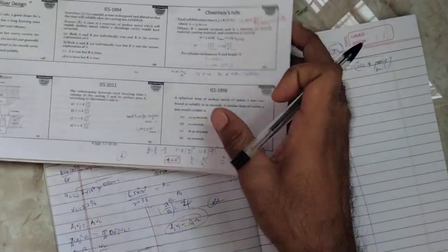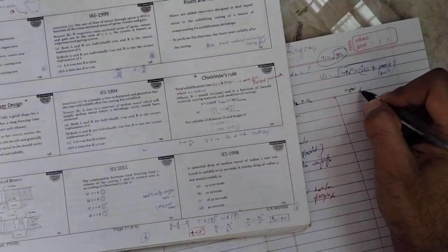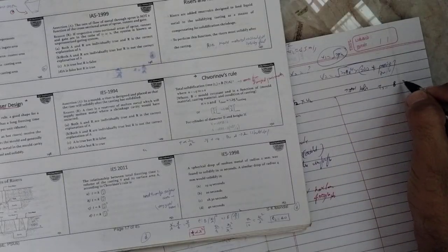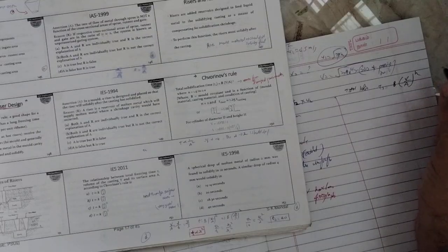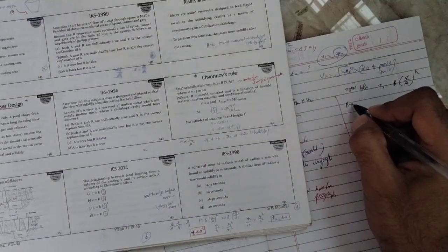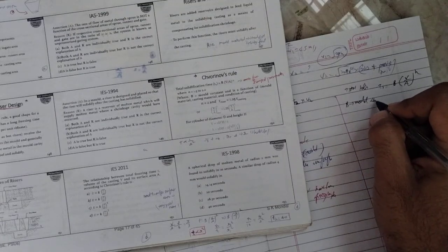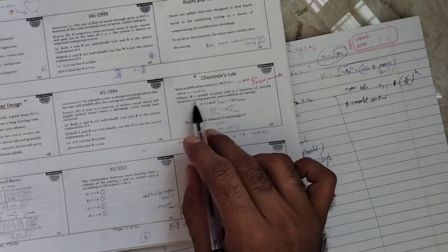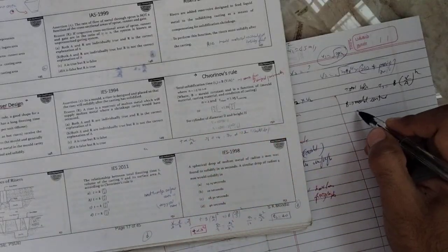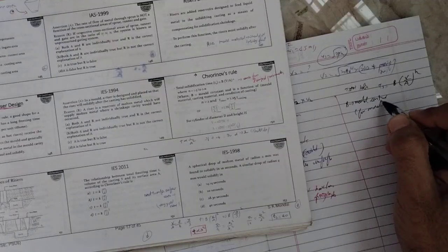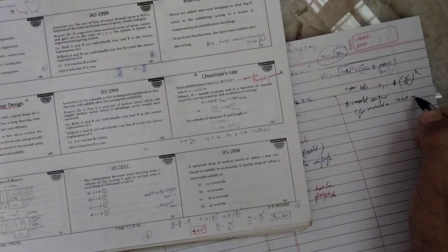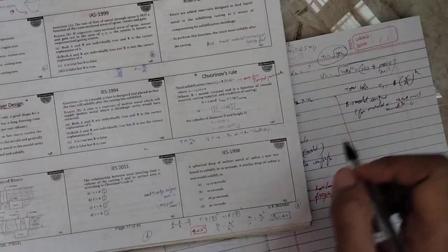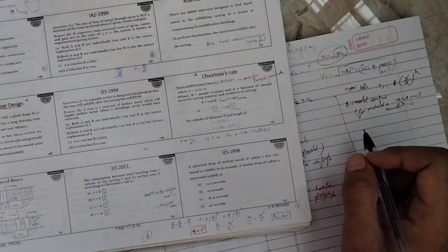So total solidification time Ts equals B into (volume divided by area) to the power n. You can see B is the mold constant and is a function of mold material, casting material, and condition of the casting. So B is a function of the mold: which shape of mold you are using, mold material, casting process, casting material, and the condition of the casting. It means it depends on the surrounding environment condition of casting. So I think you are getting the point.